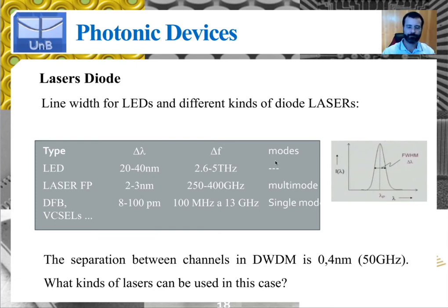And usually you don't define a waveguiding structure in most cases. So on this table here, the last column is showing the character of the laser, if it's a multi-mode or single mode or single frequency laser. So this doesn't apply here. But then we saw the Fabry-Perot laser, and in comparison, the line width of the Fabry-Perot laser is at least one order of magnitude smaller, right?